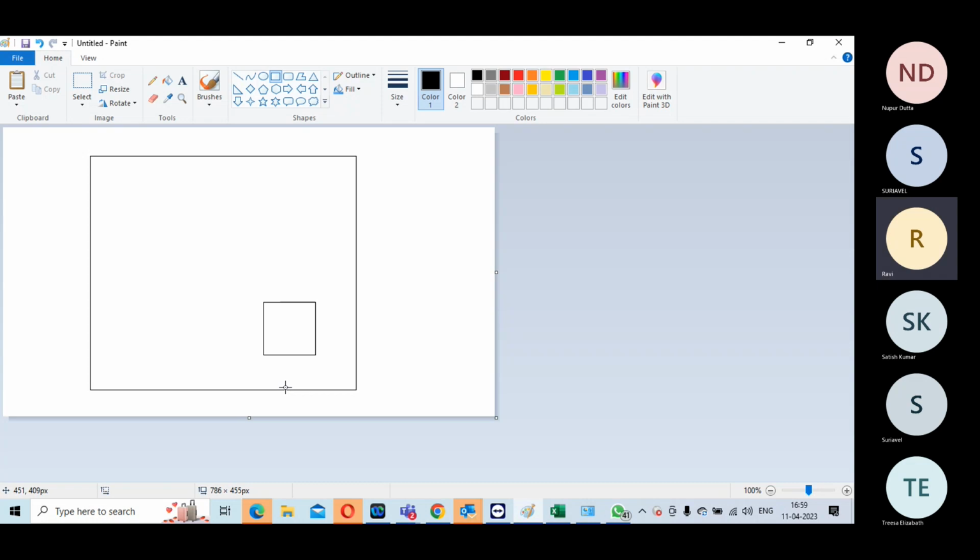You have to be very clear. Removing a buffer means somewhere the previous cell delay is increasing a lot, so it's not logical. VT swapping is one option. You can swap HVT to SVT, LVT. That is one option. What other option, without touching the cells?